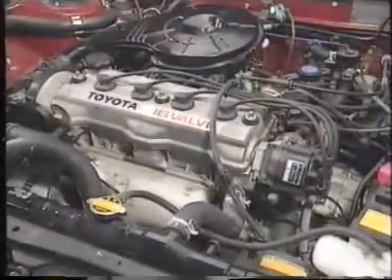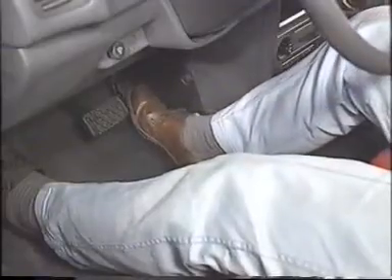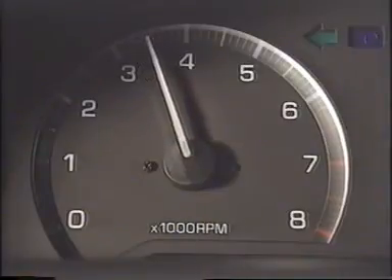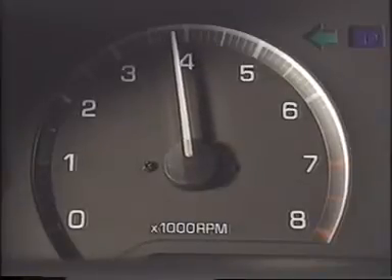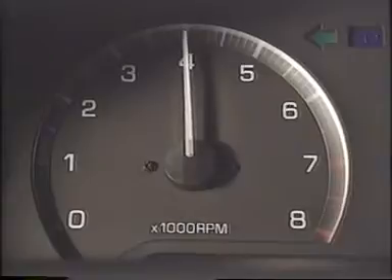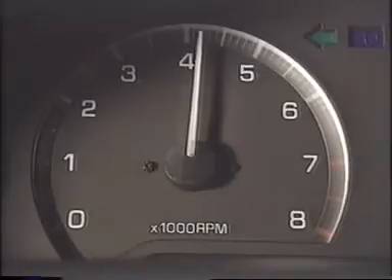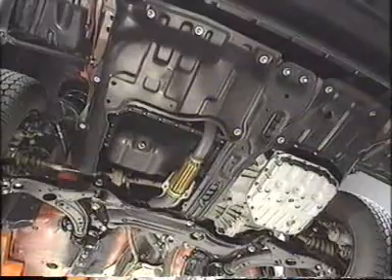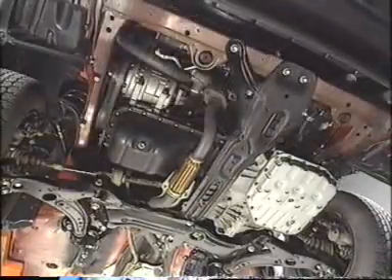The engine, too, is a major source of vibrating force. The torque fluctuations due to combustion in the engine create a vibrating force. This may also cause booming. We will now study the mechanism by which these vibrating forces lead to vibration and noise. For this purpose, we will study how the engine causes booming. The owner of this car complained that booming is heard when the engine is running at about 4,200 RPM.